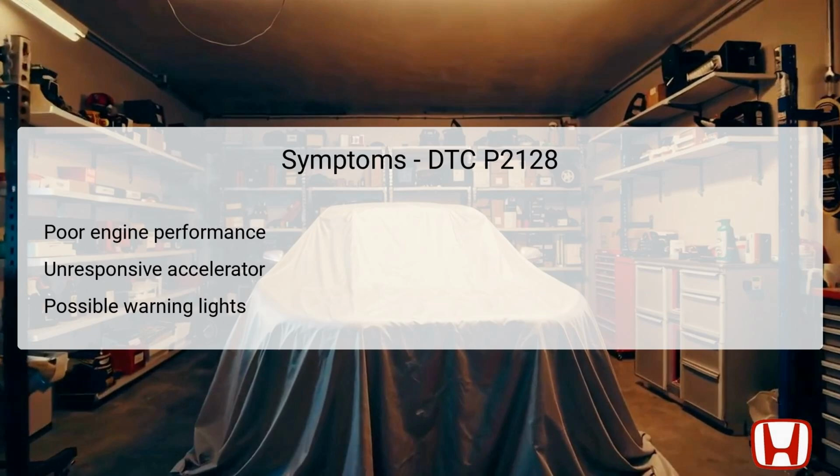Symptoms associated with the P2128 DTC can significantly affect driving experience. Poor engine performance can manifest as rough idling, hesitations during acceleration, or even stalling, jeopardizing vehicle safety. An unresponsive accelerator is a critical warning sign, as it indicates that the driver's input is not being registered by the PCM, which can lead to dangerous driving situations.